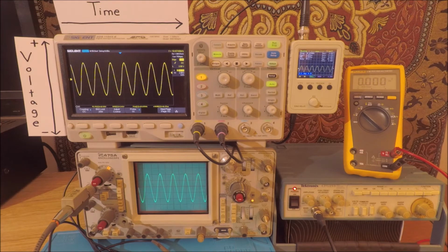If you're unfamiliar with how an oscilloscope operates, when you first approach one, they might appear a bit daunting. But all oscilloscopes share the same fundamental features. In fact, if you can locate and operate 3 controls on an oscilloscope, then you can pretty much drive any scope that's out there. The first primary control to look for on the oscilloscope is known as the volts per division control, or otherwise known as the vertical scaling control.